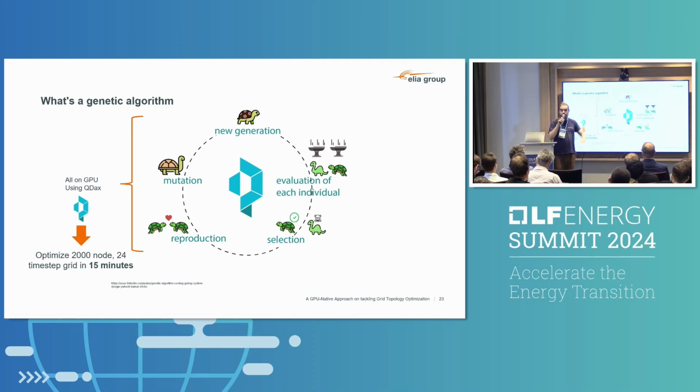So let's say we would load a line up to 99%, there's a very high chance that under changing load and generation we would violate something, that we would get a new congestion. So we make sure that we have a more conservative burden. We optimize to below 100%, sometimes to 95, sometimes to 90, depending a little on what we look at. So it's a sensitivity-free approach, meaning we can't really say why the optimizer is doing what it's doing. But in the end, we can prove on the load flow computations whether it's a good or a bad topology. So we actually do a full analysis every time.